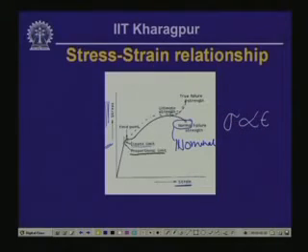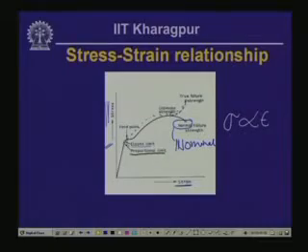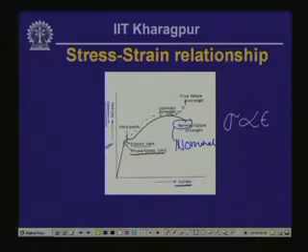And yield point is the point when the body starts yielding. It goes beyond the elastic limit, plasticity starts forming in the section, and if we keep on applying load, in fact without increasing the load, the bar deforms, the extension becomes excessive, and it reaches a stress which we call the maximum stress.